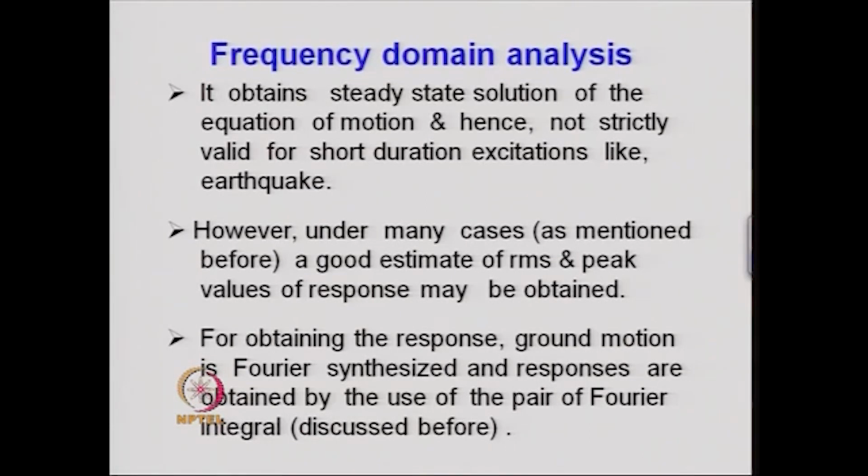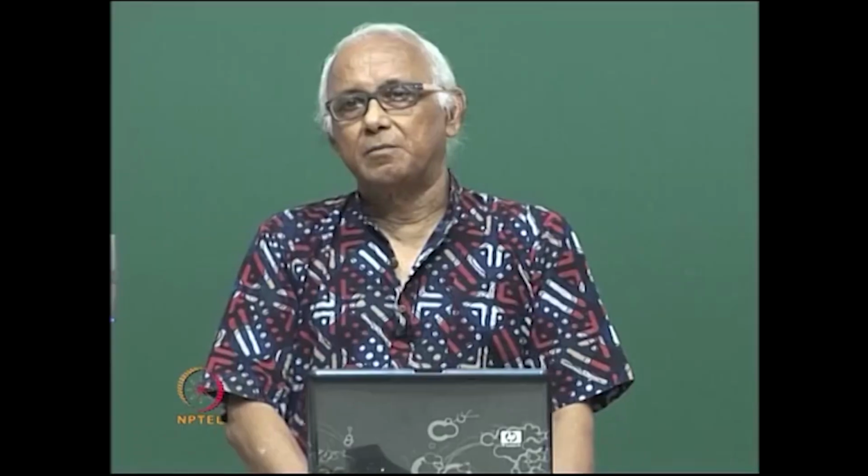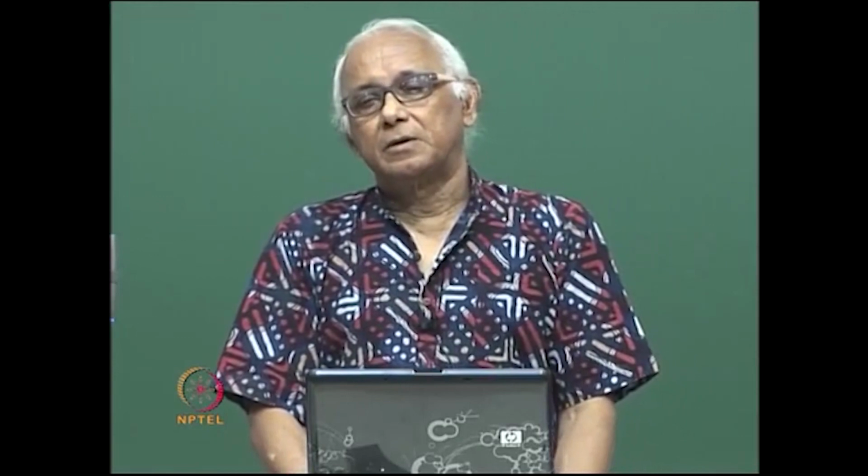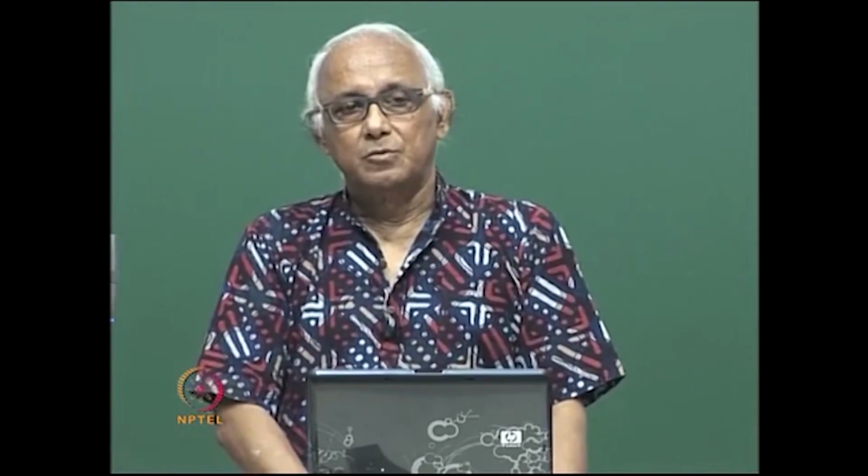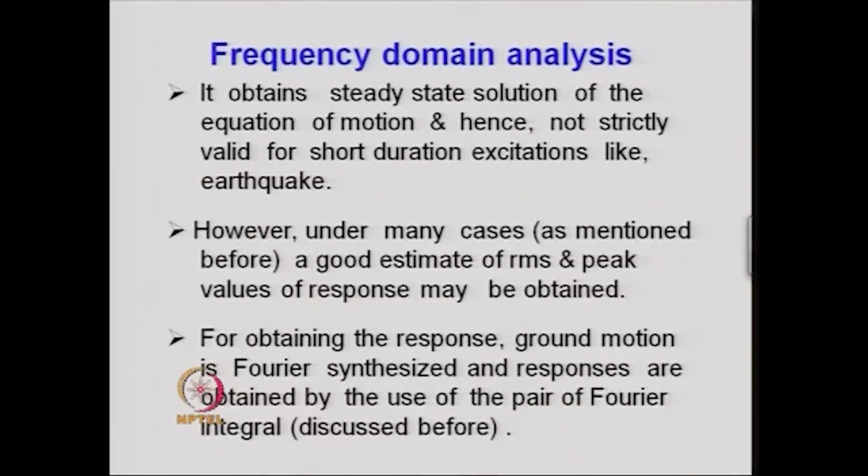The influence of the initial condition, that is the transient part of the solution, plays an important role, because for the short duration excitation, the interval of time t for which the free oscillation takes place, there the free oscillation may not become very small or may not die down. Therefore, the steady state solution using frequency domain analysis may not be applicable for short duration earthquake.